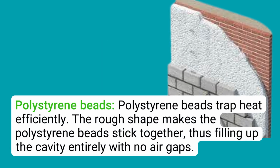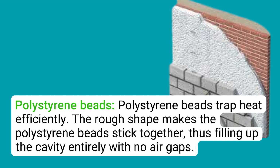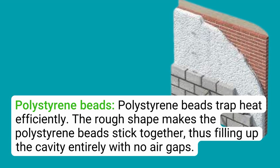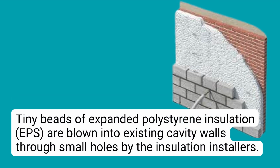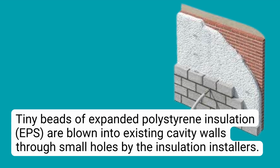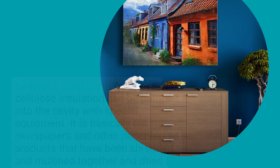Polystyrene beads. Polystyrene beads trap heat efficiently. The rough shape makes the polystyrene beads stick together, thus filling up the cavity entirely with no air gaps. Tiny beads of expanded polystyrene insulation are blown into existing cavity walls through small holes by the insulation installers.